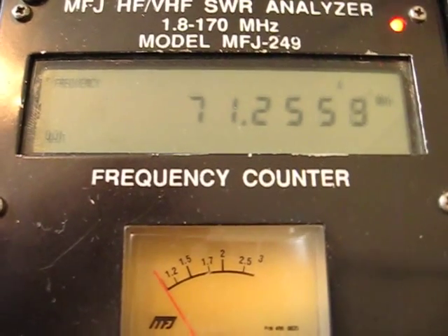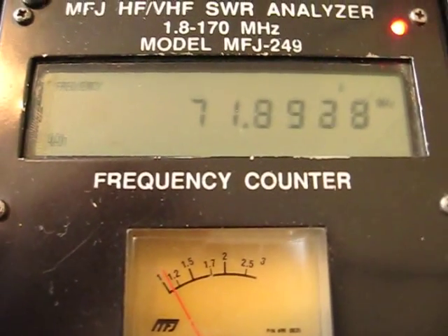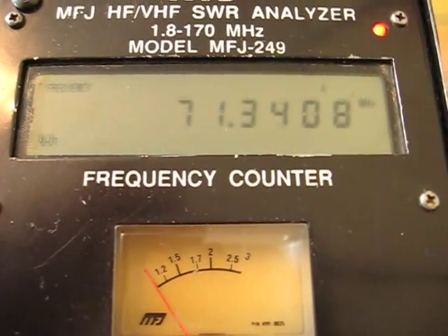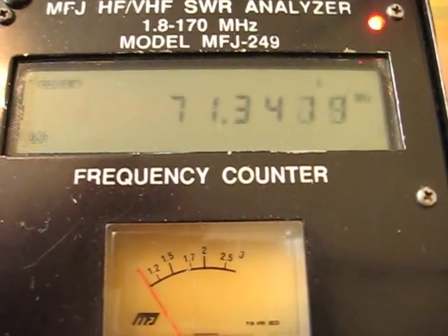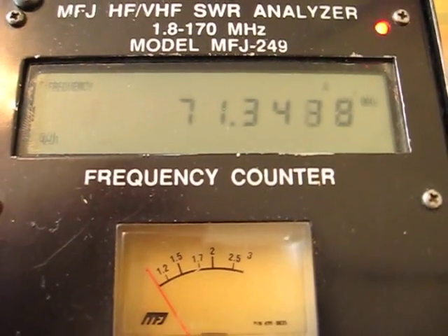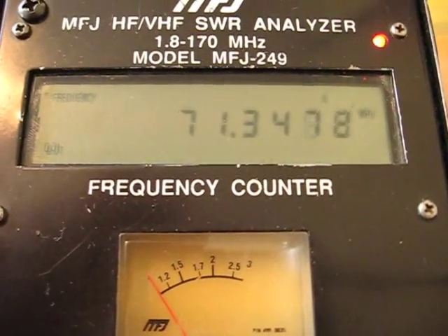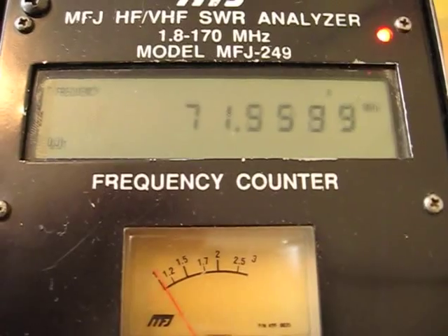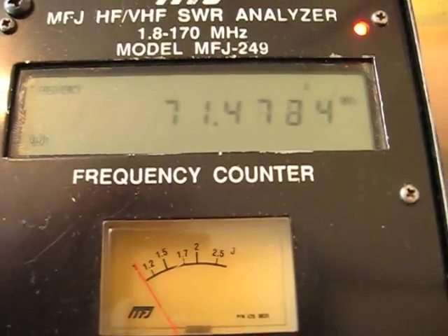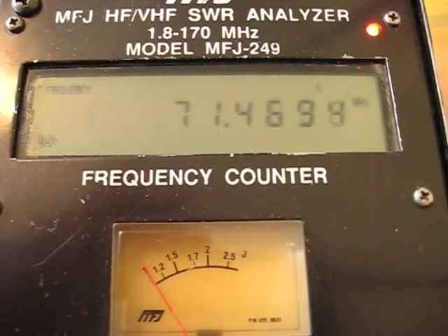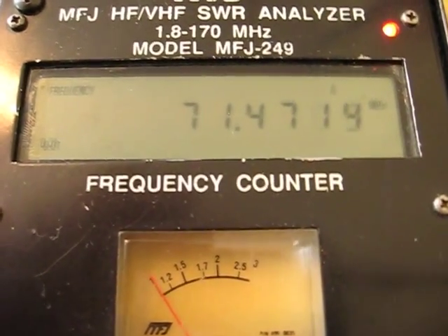You can either go very close to the antenna and check for impedance, but that's impractical, really, isn't it? So you need to be a fair distance away from your antenna, but you want to know the exact impedance at the terminals of the antenna, and the only way to do it is have coax to this antenna analyzer in a half wave or multiples of.